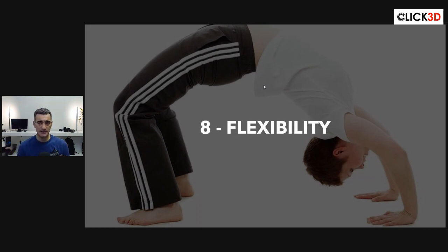Now, the laser scanner is also pretty good. For example, you can mount it in holes. You can use it in very dark places. So if people are doing sewers or tunnels and things like that, you don't need any lighting. You can mount it upside down, and that's okay. But you can't really mount it on a moving object. It's not really intended for something like that. So, in terms of flexibility, digital camera photogrammetry has a little bit of an advantage.